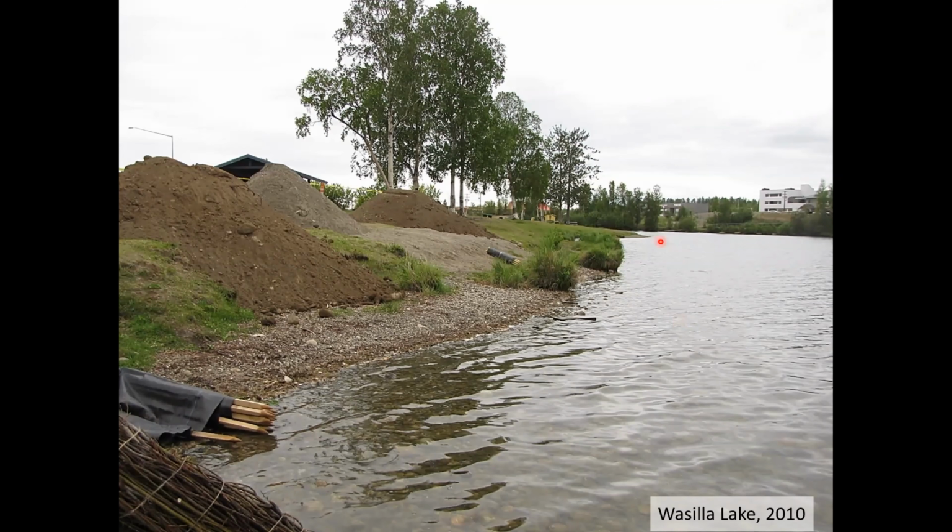And in this area is where everyone comes to swim. And so the park decided to try to get something done here. Note, you'll see right here, we've got the willow bundles actually soaking in water. It's really good to soak your willow bundles for 24 to 48 hours at minimum. The longer you can get them soaked, the better survivability they have.